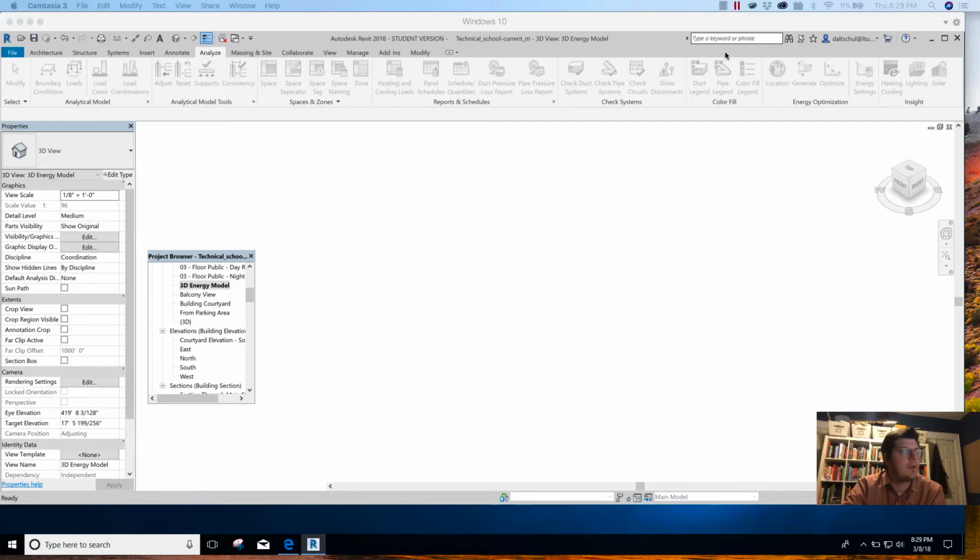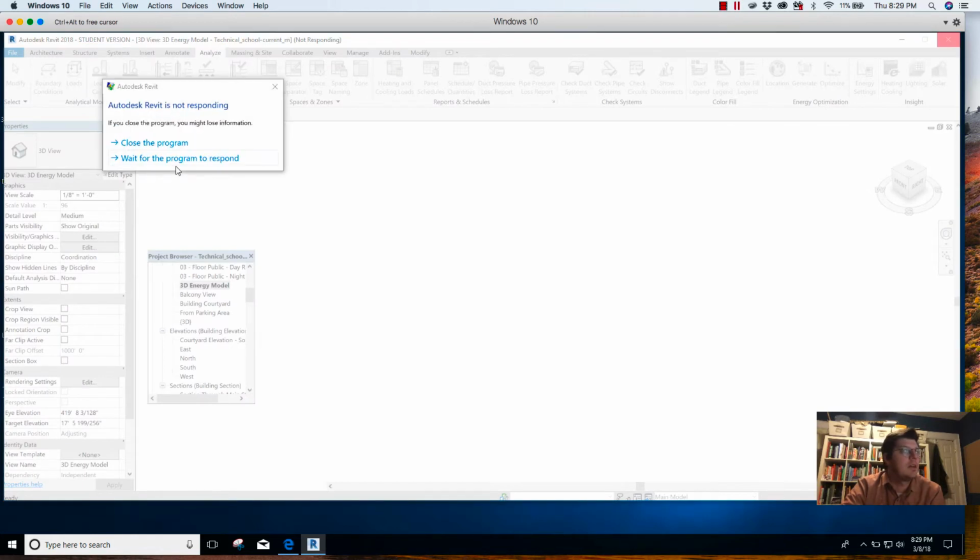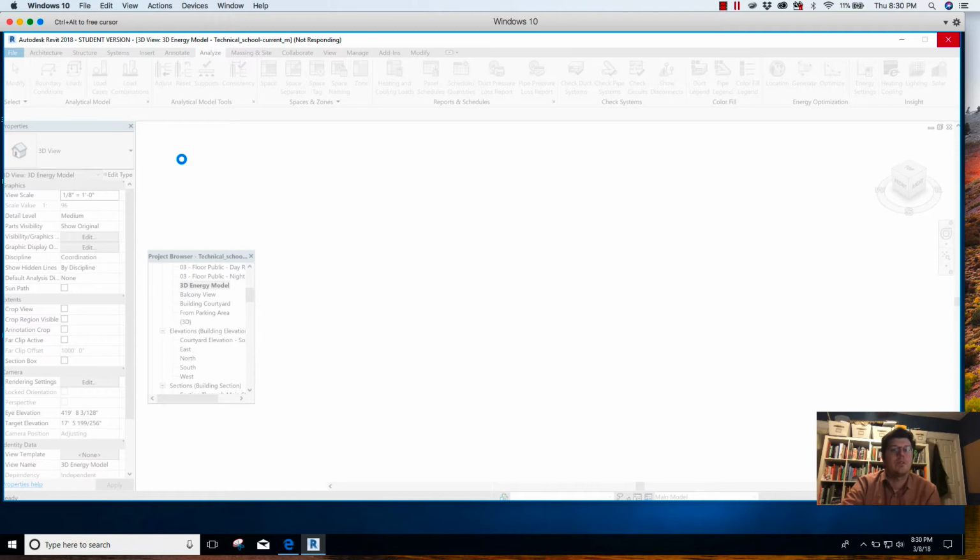Another thing too that maybe I didn't make enough of: when you're adjusting the material properties for the thermal values, they can literally be anything. I've had someone that used rammed earth before, so we did research on where the thermal value of rammed earth comes from and how we really get Revit to account for that in the most accurate way using energy modeling.